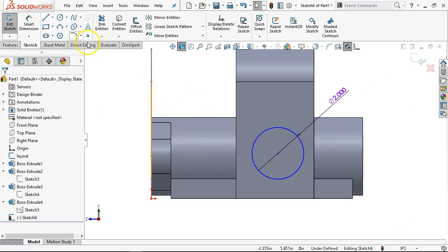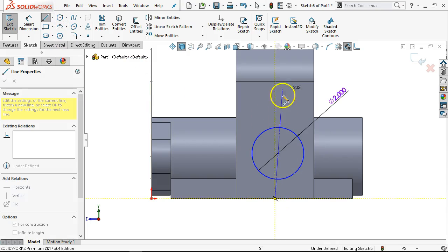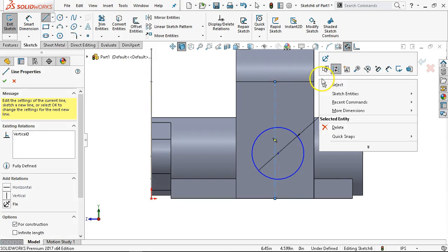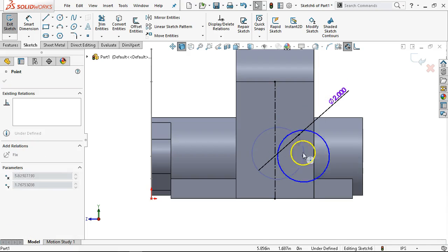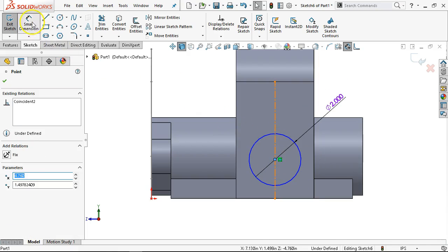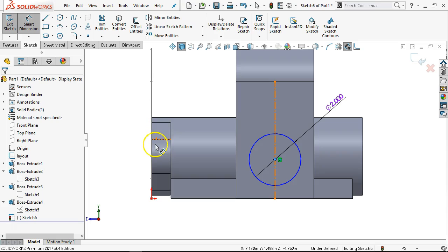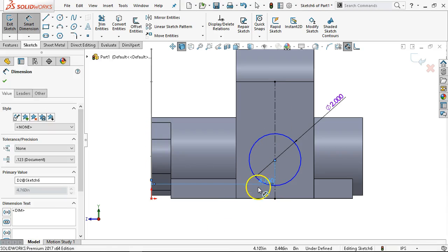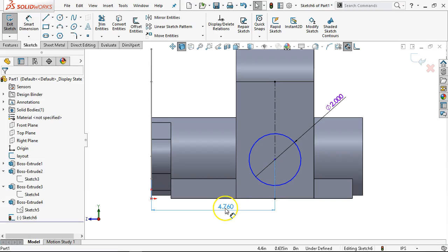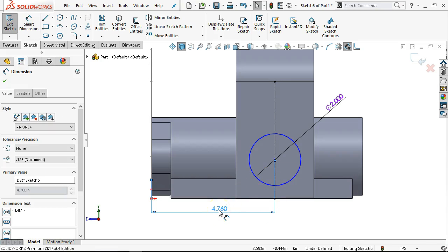And position-wise, we can double check. I'll put a center line in place. And for my double check, I'll go from the front back to center. I know that that's going to be a driven dimension, but I want it to be able to travel with that geometry.